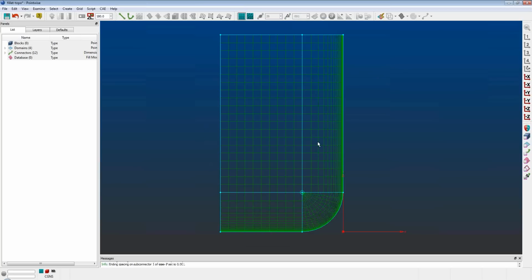So already at this point, the grid looks a lot better than the H block approach, but poles aren't what we'd want for a couple of reasons. First, and maybe the most obvious, is maybe your structured solver just doesn't support poles. This typically isn't a problem for unstructured solvers because the cells around the poles are converted to wedges. But another issue is that the pole, in this case, introduces a large jump in cell size.